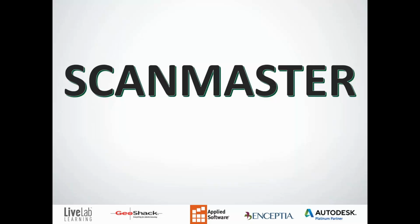Move the instrument to a control point, backsite a different control point, any of the ones that are in our list, scan again. So if I have 7 or 8 scans at the end of it, I'm going to take those back, and I'm going to go ahead and go into Scan Master.